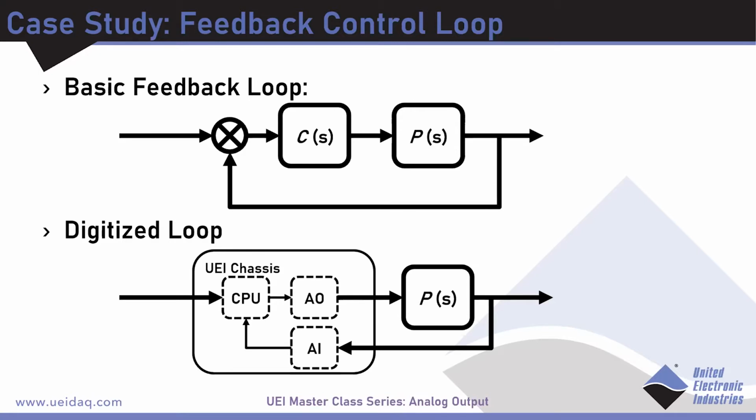So what I've done here at the bottom is I've dropped in a UEI chassis, right? I've quote unquote digitized the system. In this case, the set point that we provide our adder block would just be a value we provide to our CPU. And we could use an analog output to supply an input to the plant and then read it back through an analog input.